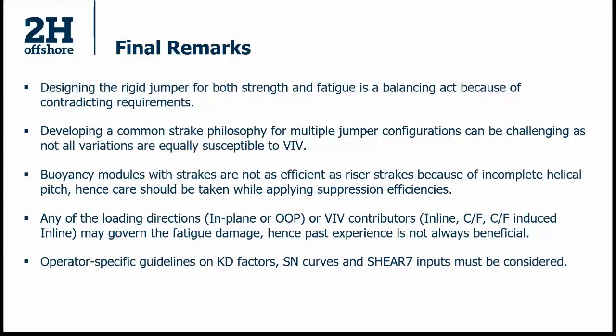Another key aspect of VIV analysis is the knockdown factors that you use, the SN curves that you use, and also the SHEAR7 input parameters that you use. And it helps to be aware that different operators have different guidelines which are very specific to their requirements. And if you have the operators on board on this analysis right from the beginning, it can be quite beneficial.